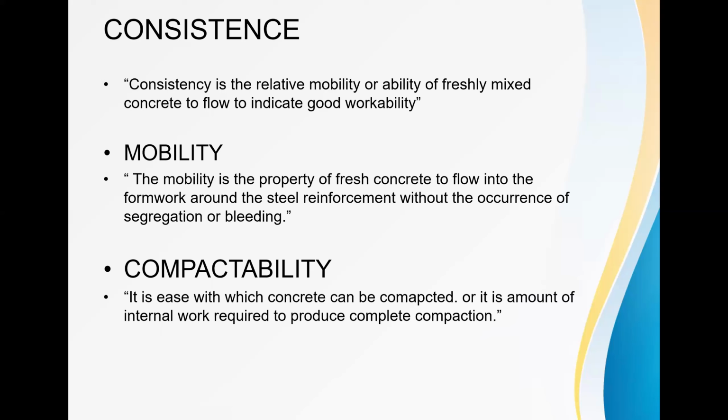Mobility is the property of fresh concrete to flow into the formwork around the steel reinforcement without the occurrence of segregation. Then what do you mean by compactability? It is the ease with which concrete can be compacted, or the amount of internal work required to produce complete compaction.